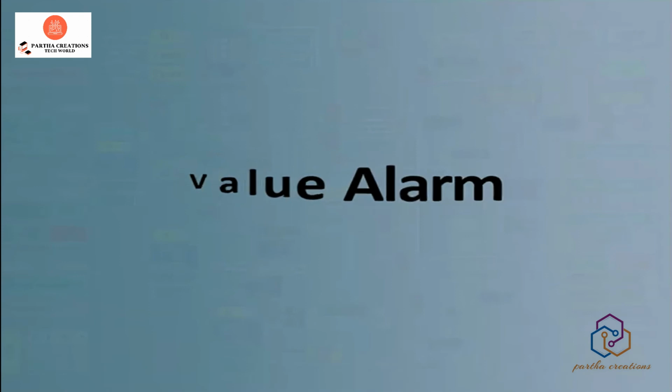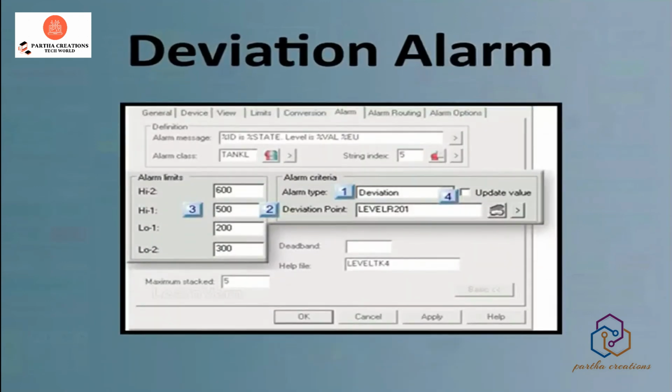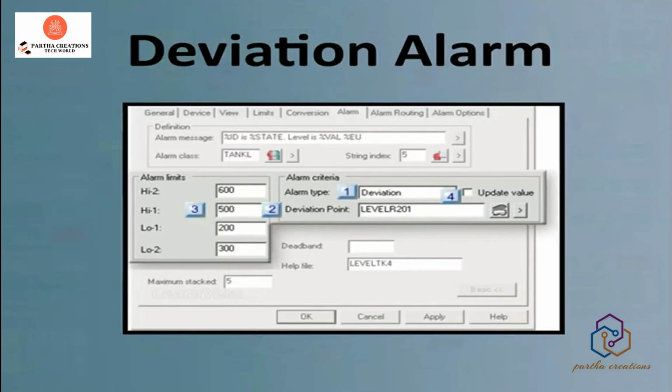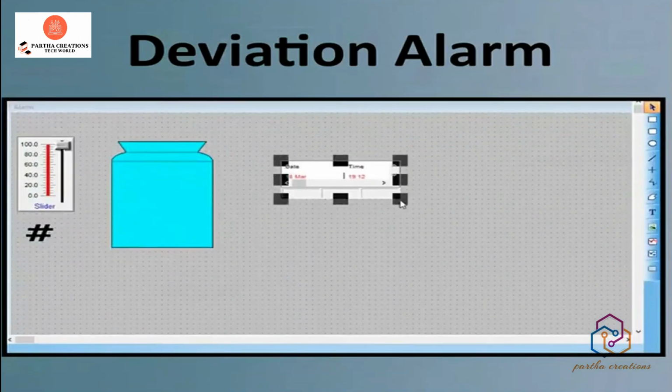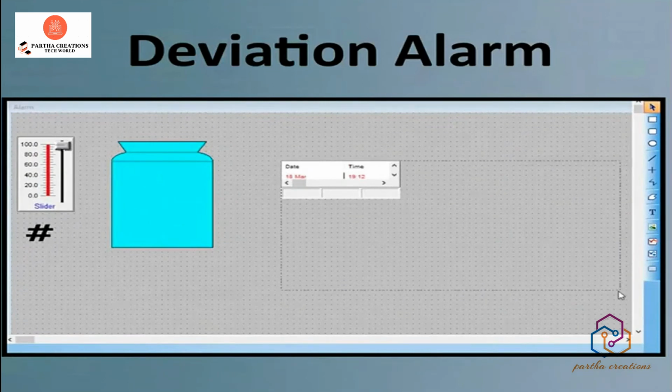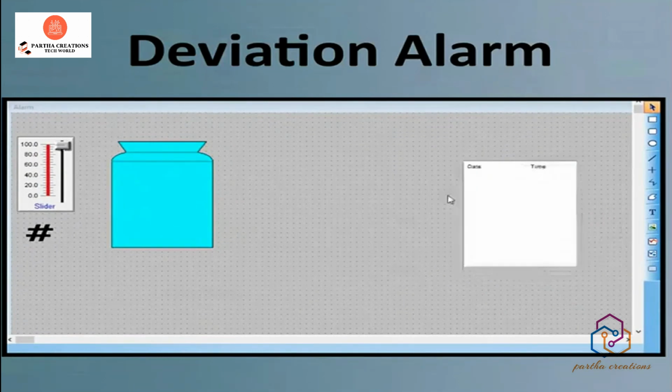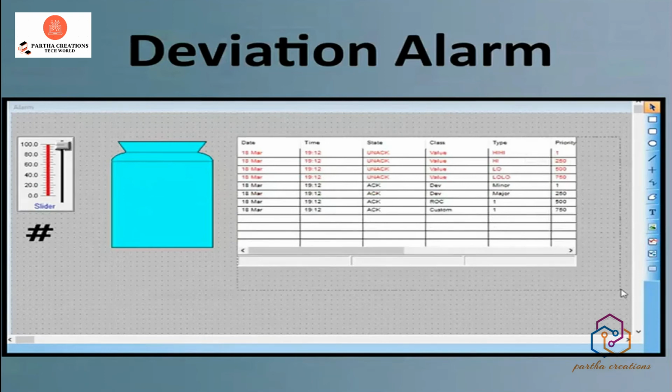The second alarm is called deviation alarm. It is related to the fluctuations. For example, if the set point is 50, then we can set a fixed percentage that if deviates over or below the certain point, we should get an alarm. Now, how much deviation do we need for the alarm to go off? Let's take an example. For the set value of 50%, we would be able to set two different kinds of alarms, that are minor deviation and major deviation.